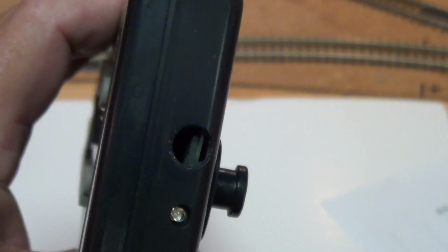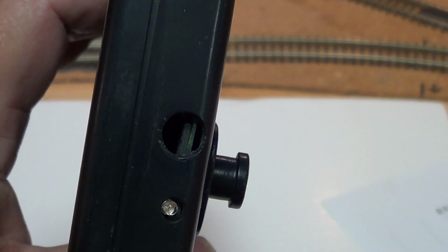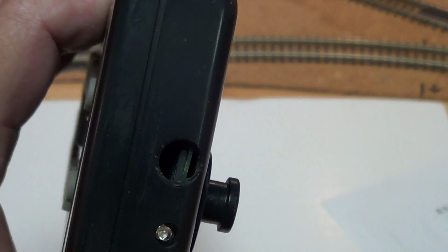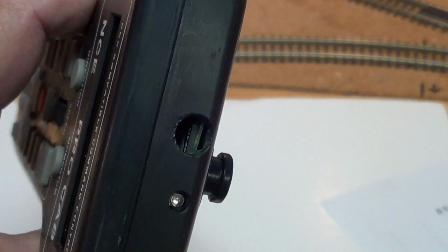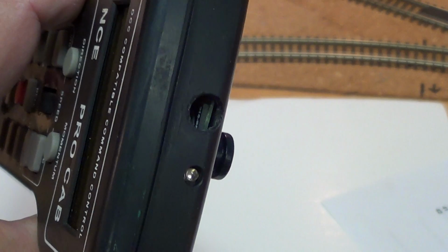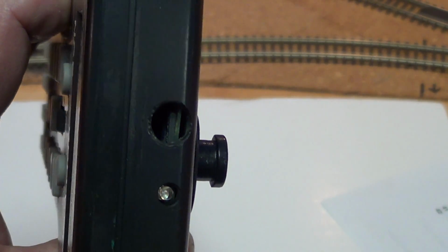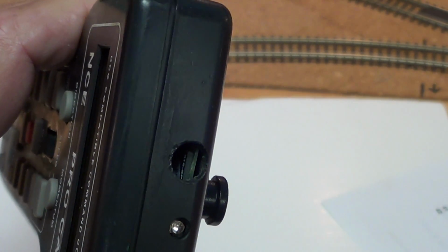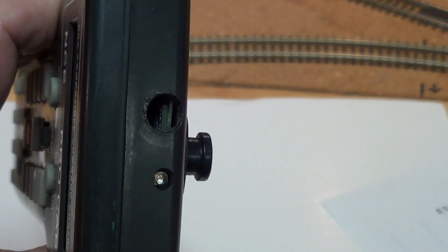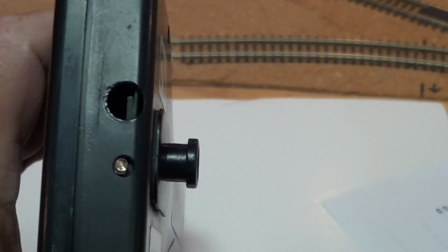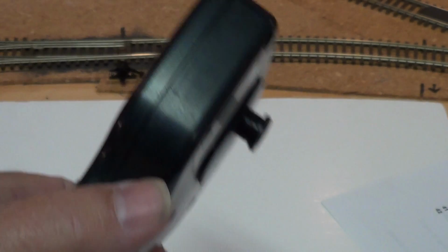There's a complete set of instructions on how to do this. It's on the internet. There's a link to it step by step. I'll only say that they talk about peeling the copper off the board with an X-Acto knife or scraping it loose, and I'm going to say, get your Dremel tool out, people. You can grind it off a lot quicker, but you do have to grind off the board to do the thing. But I've done 4 or 5 of them. They all work real well, and it sure beats trying to fix them broken off antennas. So that's an example of what an old one looks like that has been remodeled.